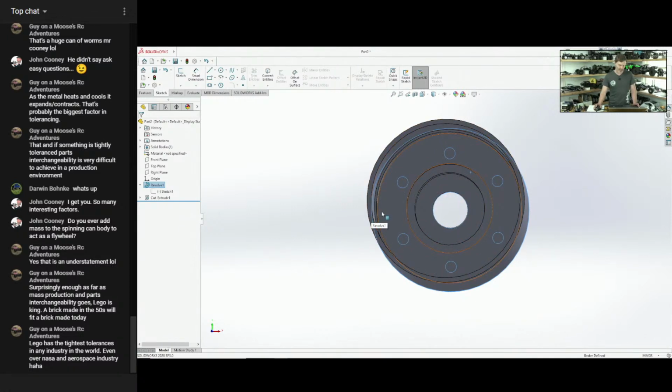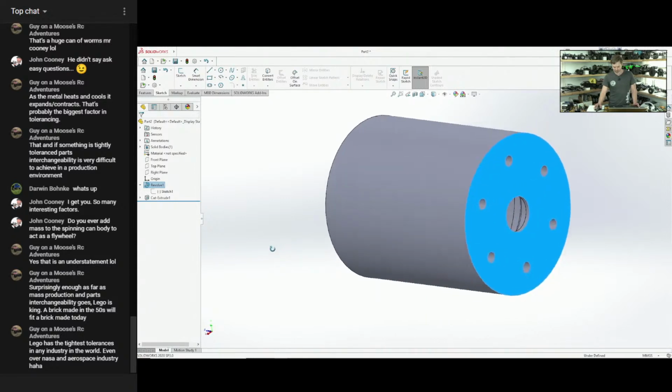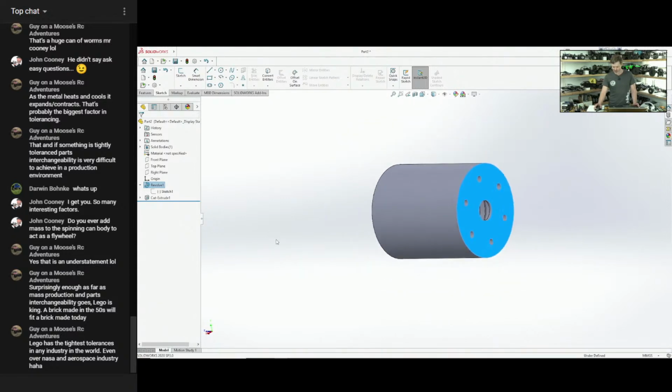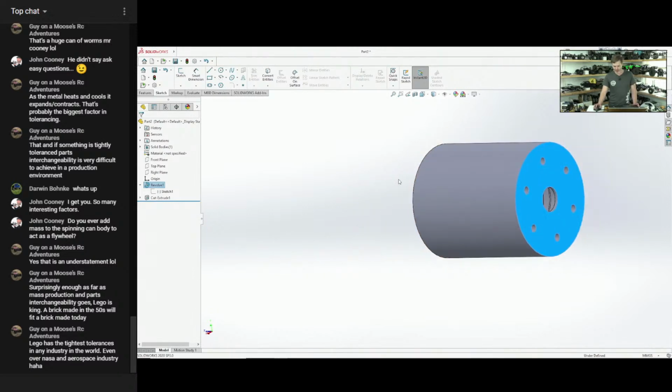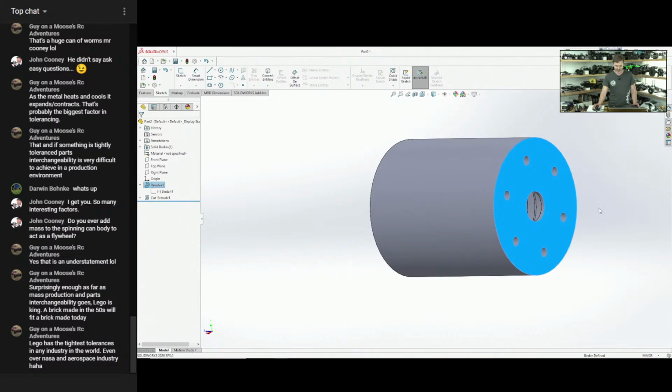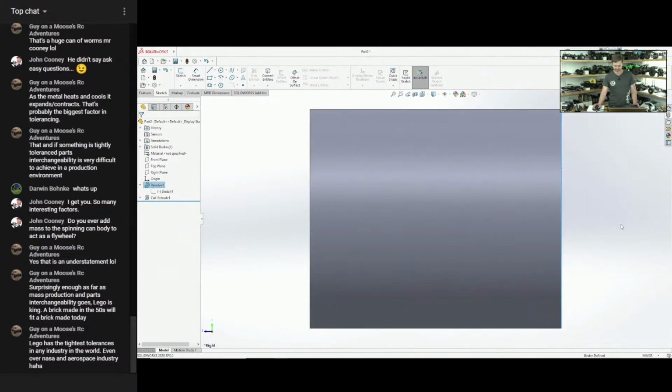And if there's 5/1000ths of an inch on the radius for tolerance, let's just call that on the circumference, so 2.5 thousandths of an inch, then that means our stator could be slid over that much, and then our rotor would actually be misaligned in the middle of the stator by that much as well. And that's going to give us a really wonky back EMF of the motor, because essentially one half of the motor is going to have a stronger back EMF than the other half of the motor, and it'll just be a mess, just a mess.